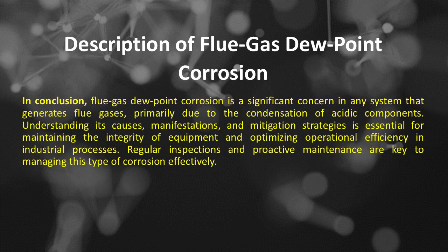In conclusion, flue-gas dew-point corrosion is a significant concern in any system that generates flue gases, primarily due to the condensation of acidic components. Understanding its causes, manifestations, and mitigation strategies is essential for maintaining the integrity of equipment and optimizing operational efficiency in industrial processes. Regular inspections and proactive maintenance are key to managing this type of corrosion effectively.